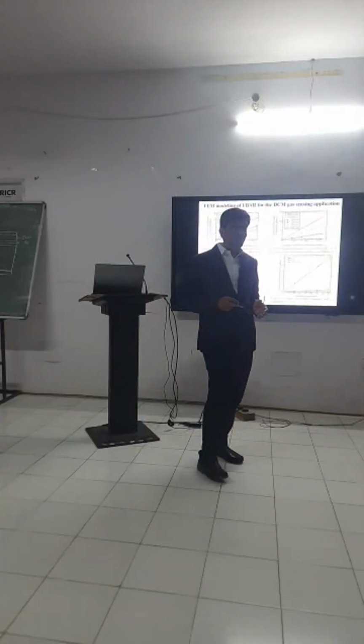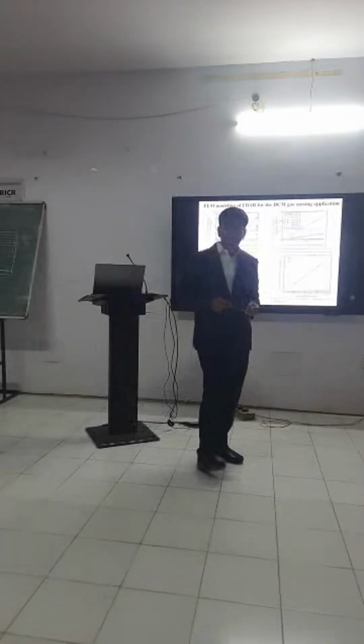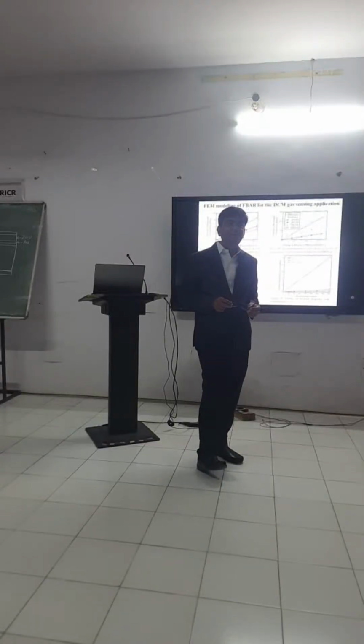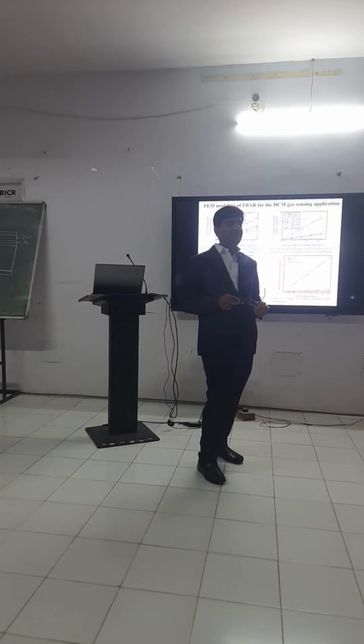What we want is to increase frequency. And when will it increase? When your piezoelectric thickness is less, because frequency is V by 2d and V is fixed. What is in your hand? Thickness. So 0.7 micron thickness will give you a good sensitivity.